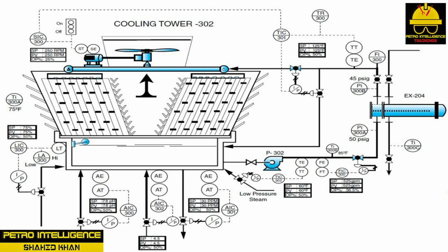Water basin is a concrete reinforced structure designed to store water and provide a foundation upon which the rest of the cooling tower can be supported. The basin is designed to collect the water as it flows across the horizontal fill and downward. The water basin provides suction for the water pump and must be able to resist chemical attack.